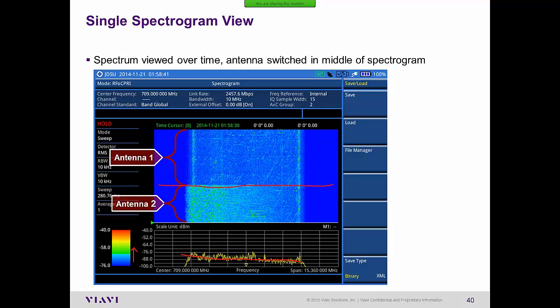Now, ideally, if you don't have access to the OCNS feature, or for Ericsson, I think most of your markets are going to be Alcatel-Lucent or Samsung, then make sure you do this at a busy hour. And if you can't take the site down during busy hour, insert the coupler in the maintenance window and then come back during the busy hour, and you can just plug into it at that point. The base station won't be impacted at all.